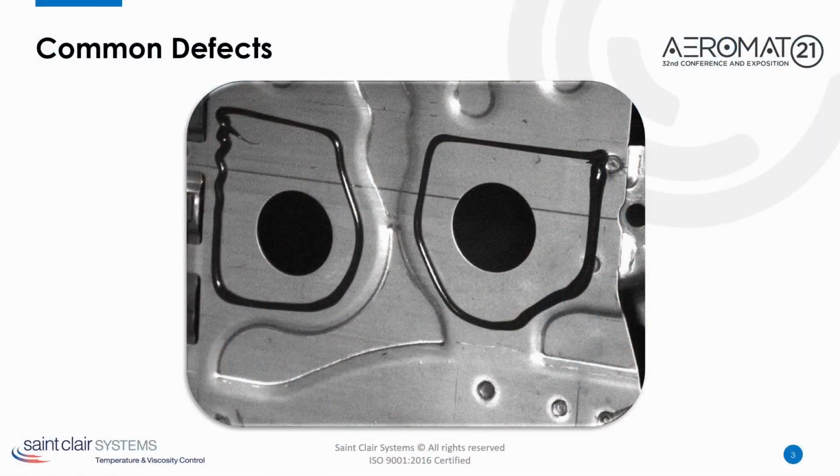In this single example, which was made by a robot in a process like the one we just viewed, we see some of the more common sealer dispensing defects. Things like thin beads where insufficient material is applied to do the job. Heavy beads where too much material is applied, which can lead to slumping, where the bead flows out of its intended area. Then there's starting blobs and ending blobs, again, where too much material is applied for the application. And finally, there's tail off, where the viscous material is dragged away after the gun is shut off.